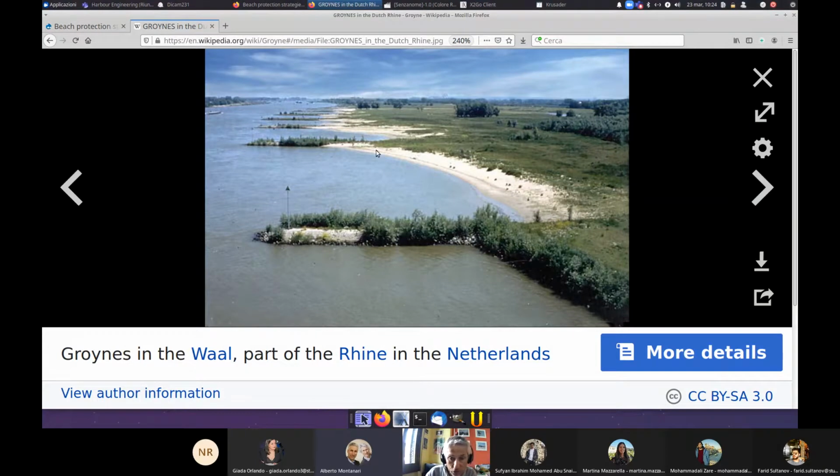You have this U-shaped beach, and in my opinion, if you remove the groins here, the coastline would move inland significantly, because I can see some signs of the coastline probably located around here, before the intervention. If you look at the shape of this, you can recognize the shape of an old beach around here.